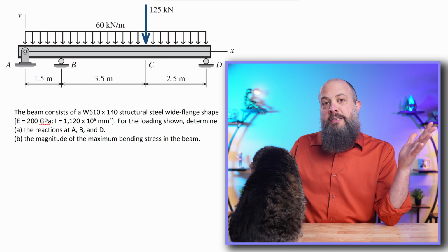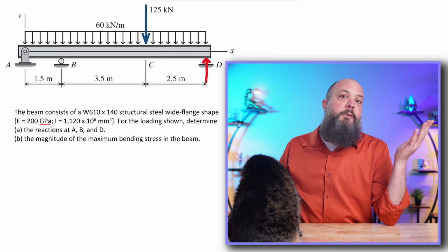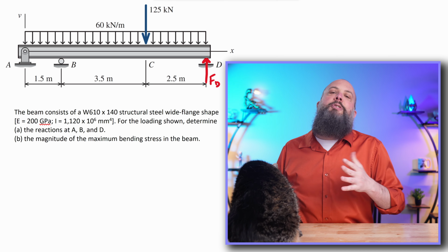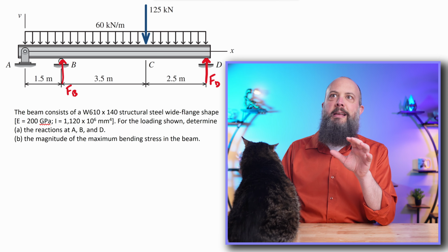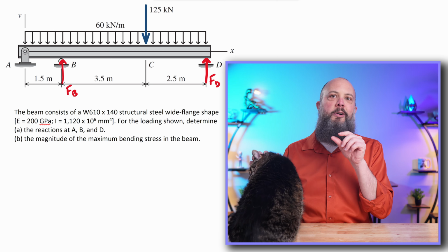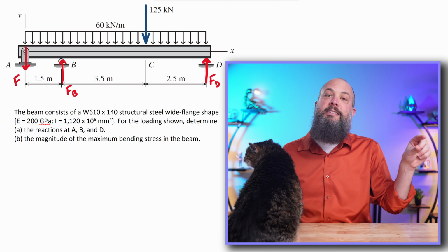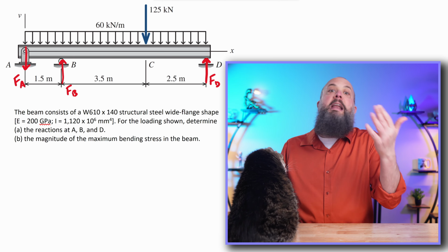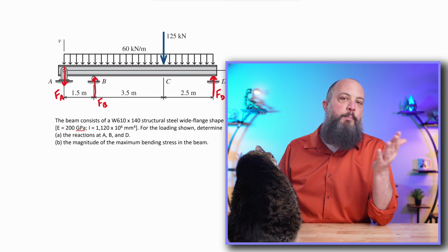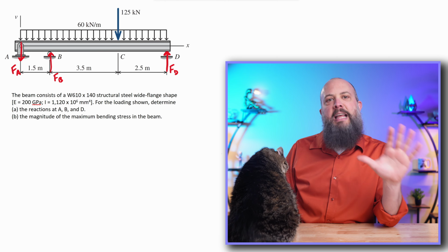So how do I know that this is statically indeterminate at all? Well, it's because there are 4 unknowns. You can only have 3 unknowns for a beam, which is usually a pin and roller or a single fixed joint, like a cantilever beam. So this has a pin and roller, simply supported, with an extra loading in the middle at B. That makes it statically indeterminate.